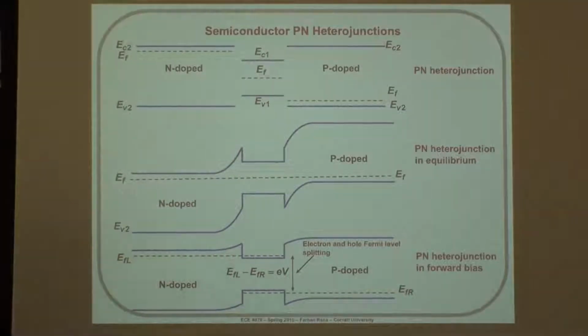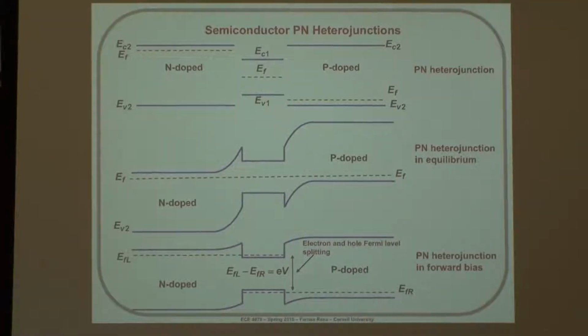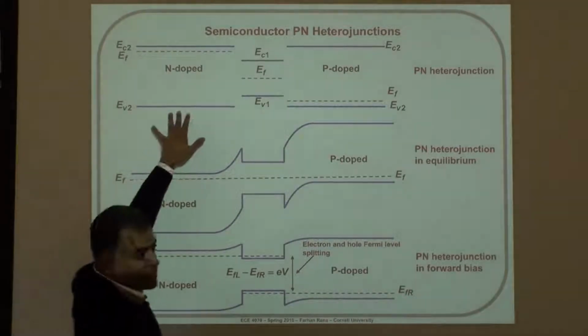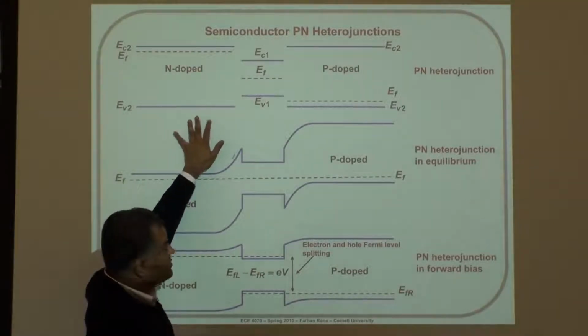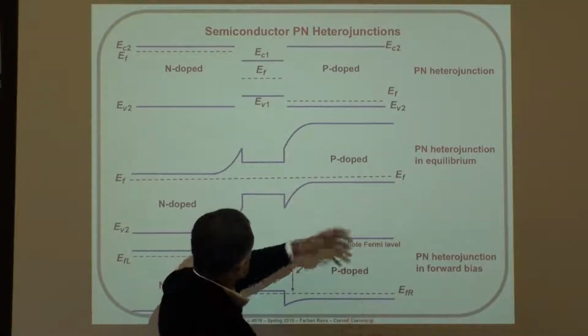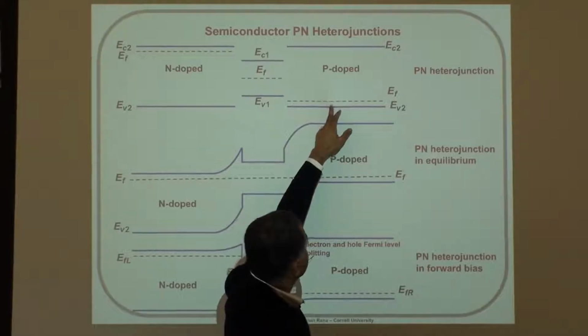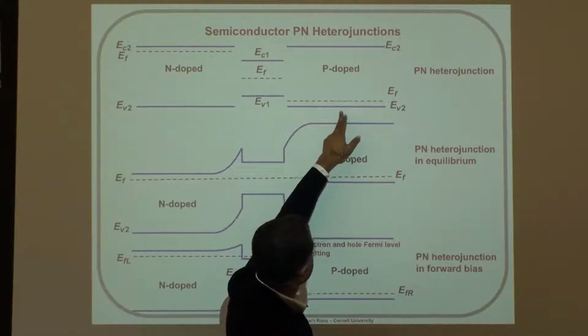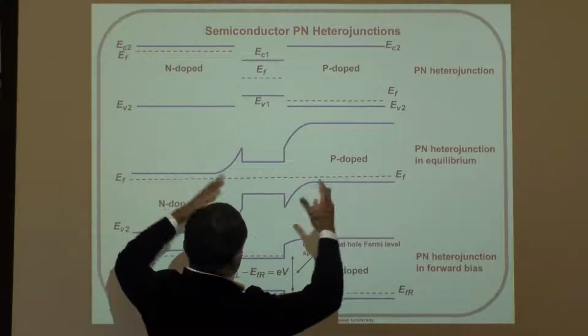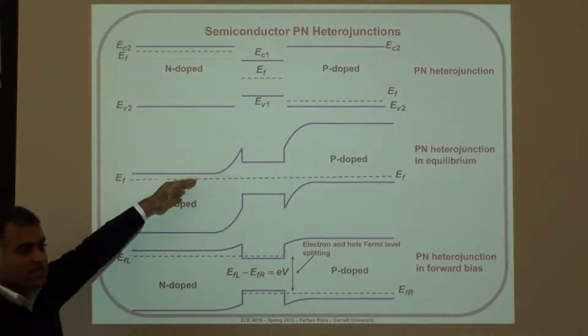inject electrons that you need to fill the conduction band, we need an N-type contact. So I have a doped semiconductor next to it, right? And similarly, to create holes in the valence band, I need to have an acceptor-doped p-type semiconductor next to it. And I put them together, my energy band diagram may look something like that.